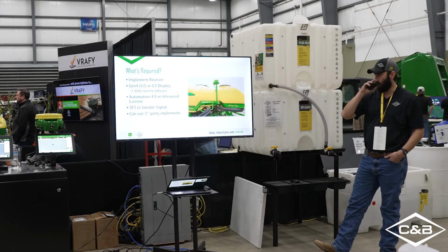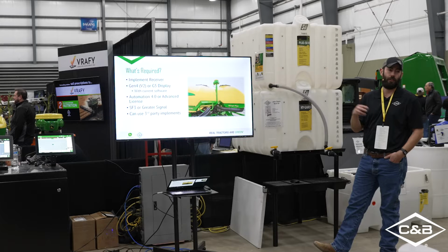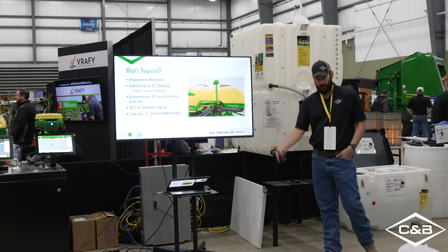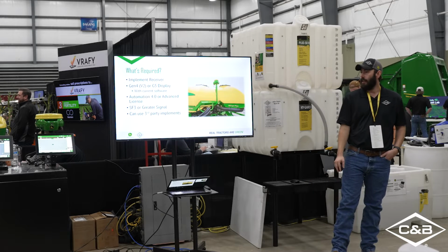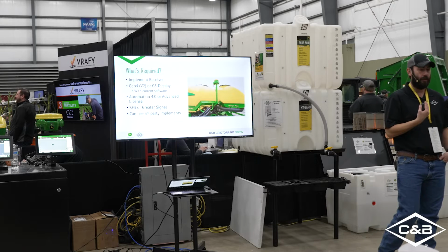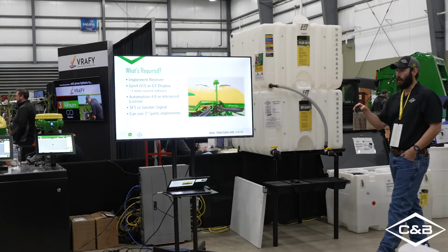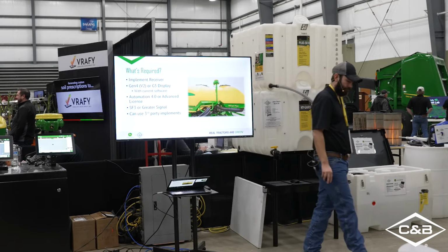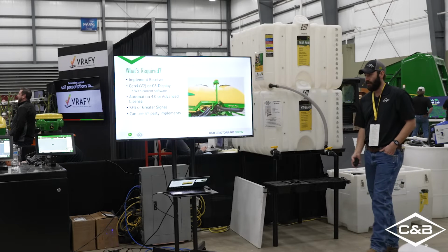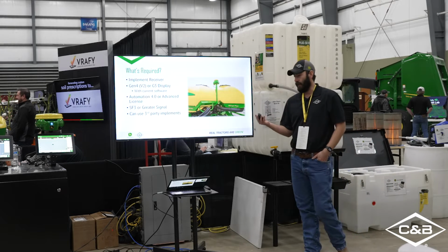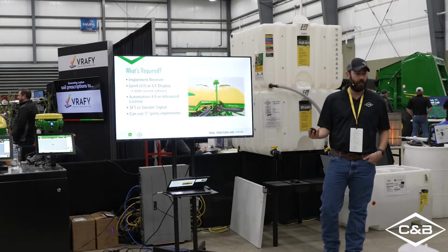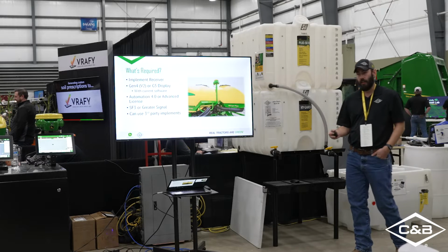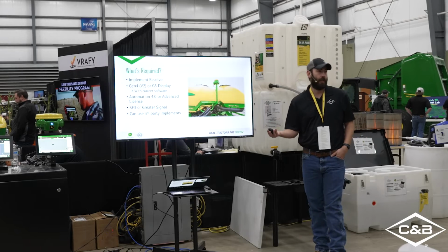Now when we say that, we want to make sure we have that SF3 or RTK on the tractor. So we want our greater signal on the tractor, and then on our implement, we can just have a 6000 with SF1 is fine to have on that implement, because it's going to share that signal back. So just remember, greater signal is on the tractor. And again, we can use this on third-party implements. Granted, hopefully everybody is running Deere, but I understand that's not always the case. I run into some guys, they have a Deere planter, but they're running Precision on it. We can still set up implement guidance on that. I even have a few guys with Kinseys running the new Blue Vantage, and we are running implement guidance with them as well.